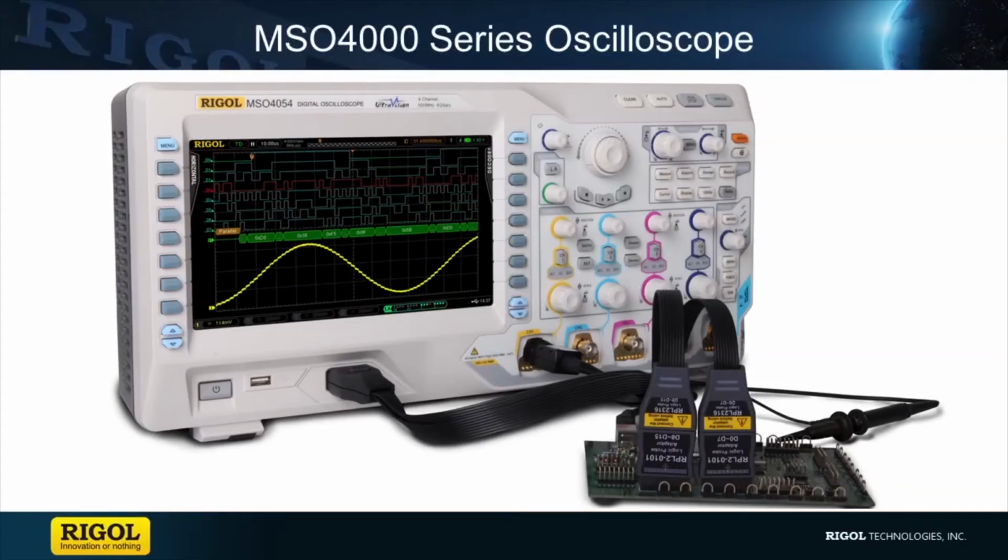We just demonstrated a couple of techniques for measuring the SPI bus on your IoT device. We used the analog and digital channels of a 4000 series RIGOL oscilloscope. Now let's look at some timing measurements we can make on the same SPI signals.